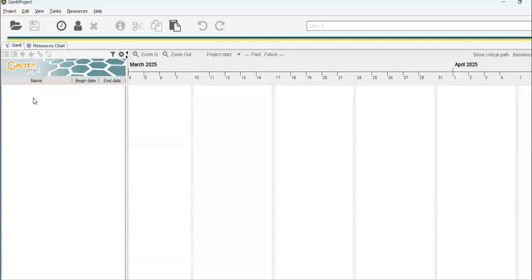You've always got options when you do this kind of thing, and you can split it up any way you want to. But I try to make it a little bit more detailed, and I try to split it up the same way that I would progress bill, because one of the features on these Gantt chart tools is that you can calculate completion percentages from the Gantt chart. Very often your client will require you to submit a new Gantt chart with your progress billing. So if your Gantt chart and your progress billing agree on the completion percentages, there's less chance that they're going to argue about what is done and what's not done. So I'm just going to show you real quick.